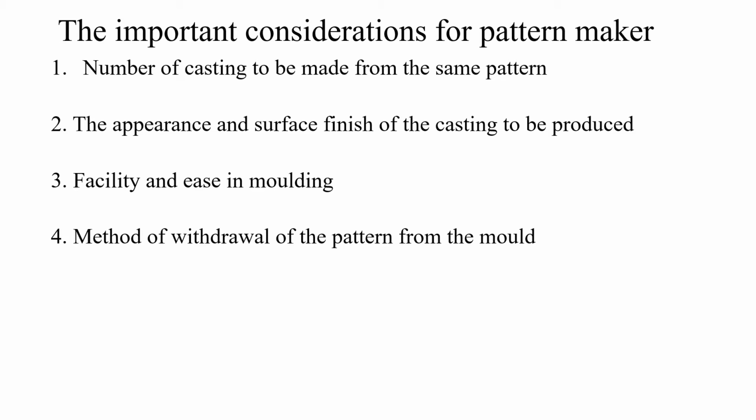So it is preferable to make a pattern which will be used several times. The appearance of the finished surface also needs to be considered. How easy is it to mold in that shape? And how will we be able to withdraw the cast part in that mold